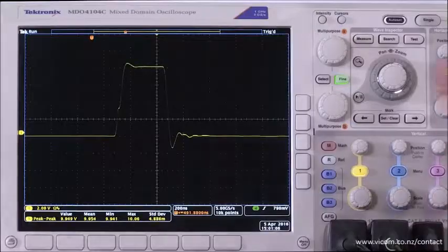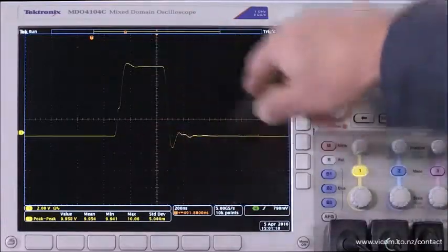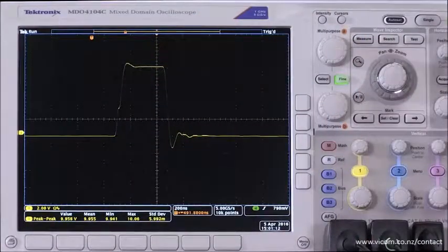Hi, I'm Mac Mindy. I'm a design engineer at Tektronix, and I'm here to show you what insufficient bandwidth does to your measurement. Here we're looking at a high-side VGS measurement. It's a 100 kilohertz switcher, and so you would think 1 megahertz is plenty to make this measurement. 1 megahertz of measurement bandwidth is plenty.